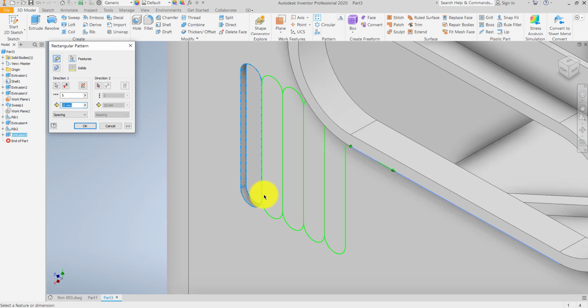So the way it works out is, remember that was 5. Remember from the center I put that 5. So it actually calculates from this bottom left. Please remember that. It's actually calculating, this 10 came from the bottom left. Whenever it's AutoCAD or Inventor or any Autodesk product, it always starts calculating from the BL. It's called BL in AutoCAD, bottom left.